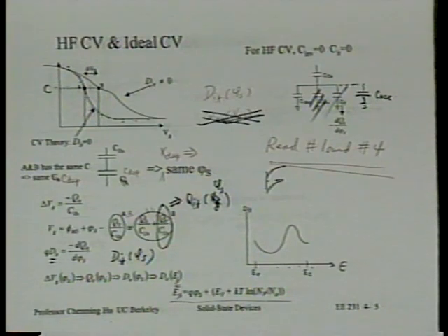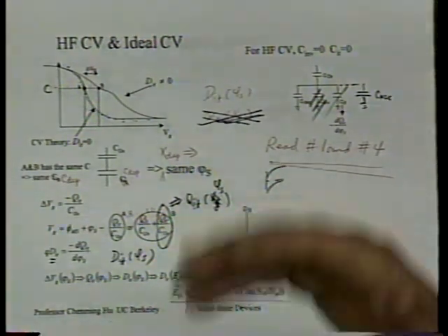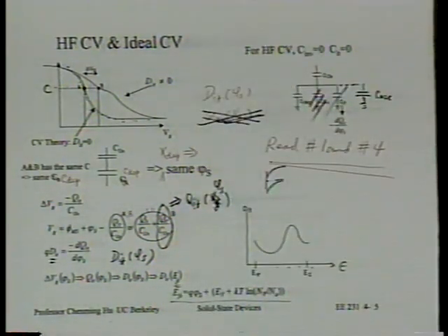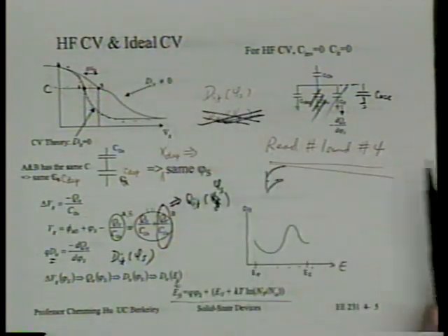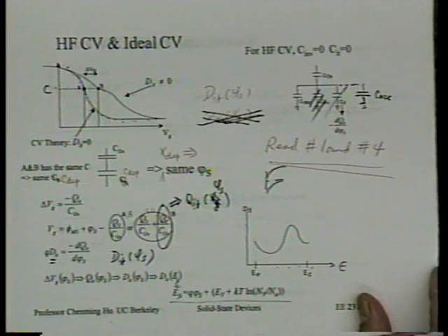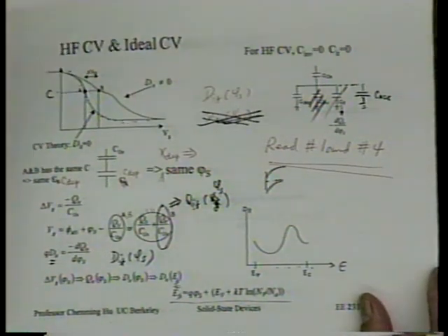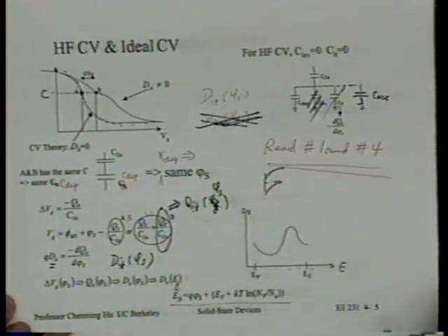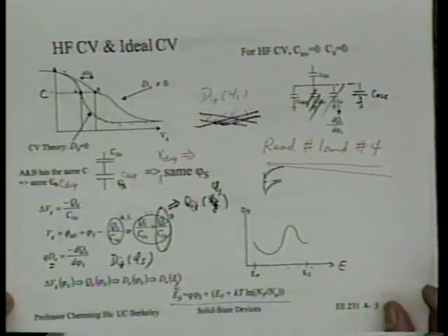Even if the inversion layer is present, there is still a significant time delay for electrons to move back and forth between the inversion layer and the interface trap. So that's significant. The interface traps would not respond to a high-frequency signal even if the inversion layer is present. So either way, this measurement can be made in the presence of the source drain.